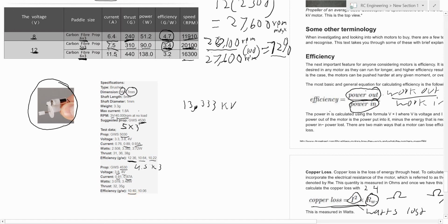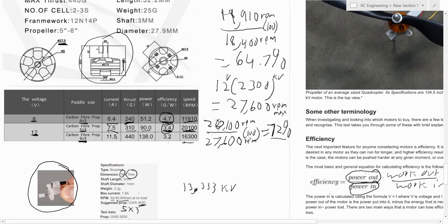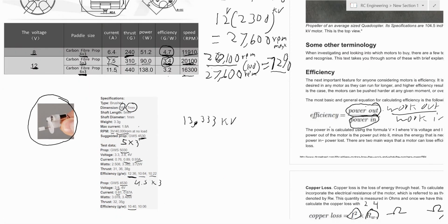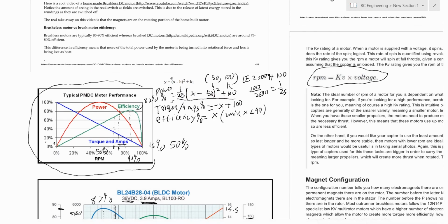And so before I end this video, I'm going to talk about how they did that to get the efficiency. And as you know, this is good efficiency because this is a brush motor compared to this guy, which is a brushless motor, which are inherently more efficient. The key is how they used the gearing. Basically, they have the motor run at peak efficiency and then slow the speed down through a reduction gearbox.